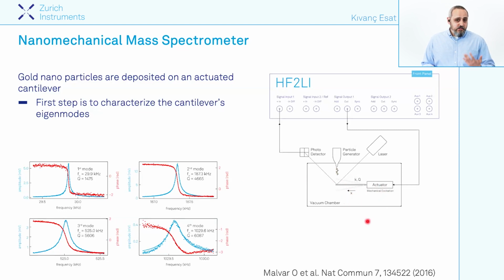It's actually a resonator device which has multiple modes, which we characterize using frequency response analysis to get a sense of where the frequencies of these individual eigenmodes of this cantilever are, what the quality factors are, and how the phase response looks like. And now, after we characterize this, we want to track this phase using multiple PLLs that run in parallel on individual eigenmodes.